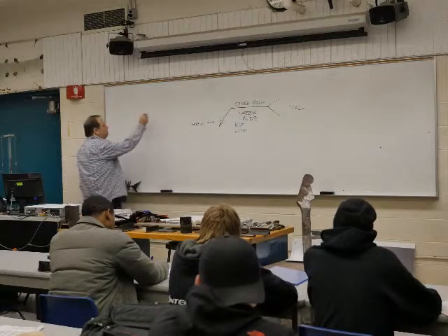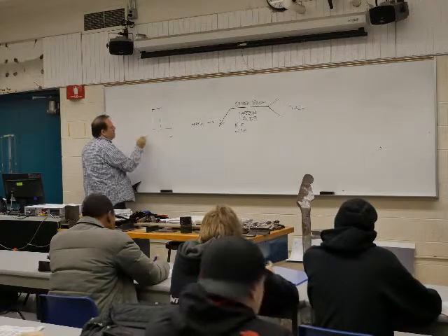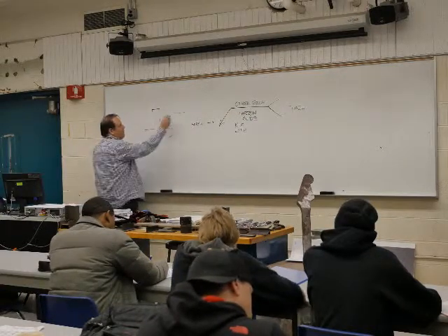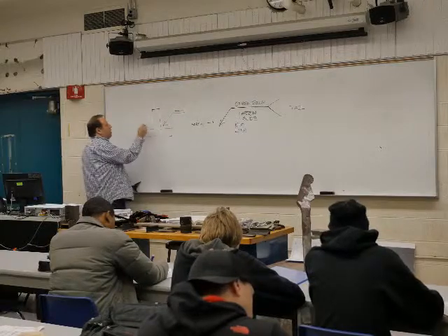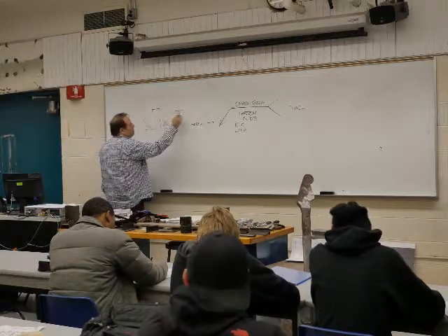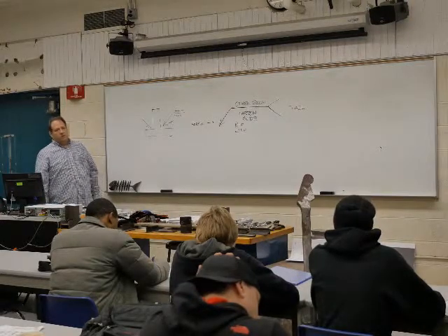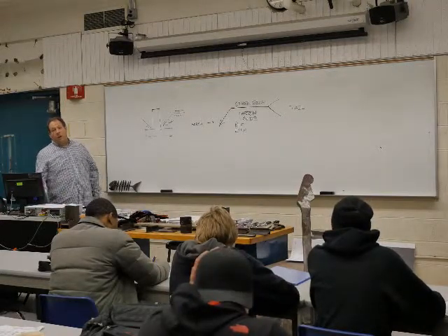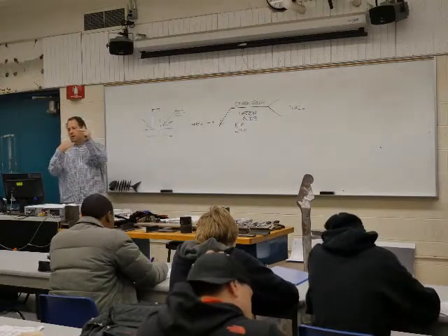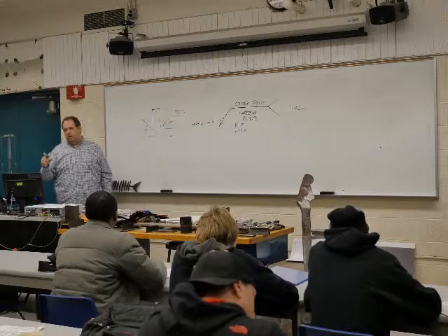So, for example, we'll do a standard T. And if we have information here, we're talking about welding on that side. If we've got the information here instead, we're going to be on this arrow side here. So that's determining where your weld is going to go. That could be doubled up. Maybe there's a weld on both sides. So you may have a mirror of the information. So either way, still referring to arrow side and other side whenever we're doing this.